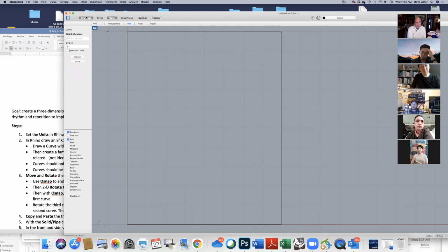I'm going to turn grid snap off so I have a little more precise control of what kind of arc I'm drawing. Now, if I draw an arc straight up and then straight over, and I have basically the distance between those 3 points fairly even, it will be very similar to a part of a circle. If I draw 2 points close together, I will accelerate. So I'll have a gradual curve and then turn more sharply at the end.